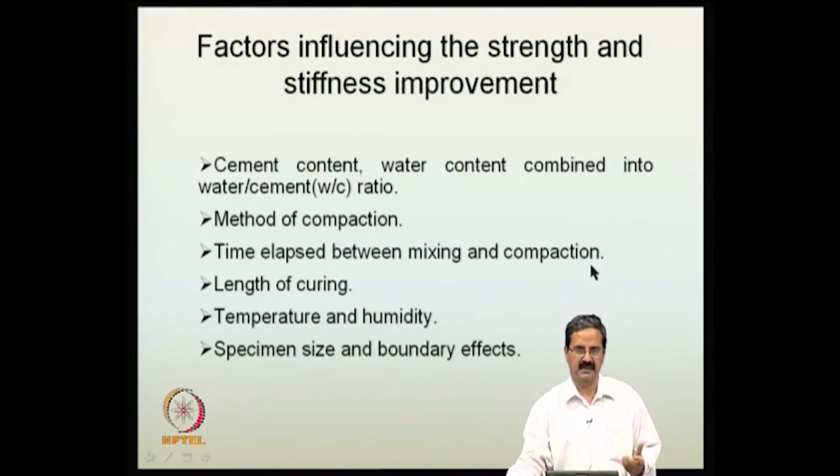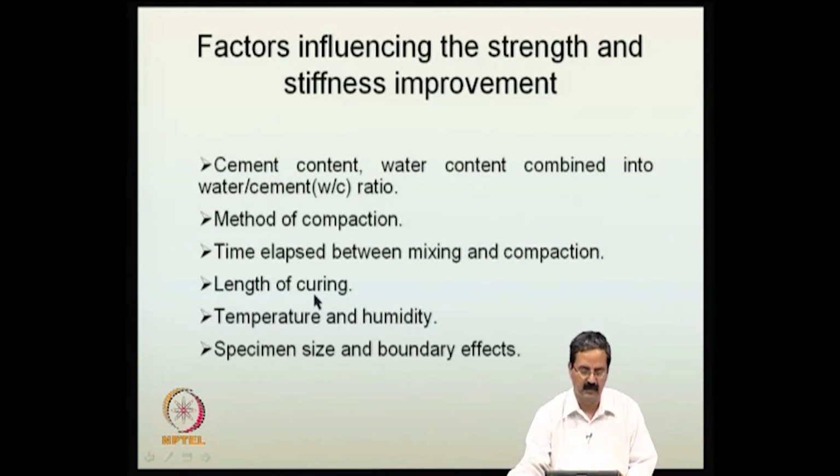If you mix cement plus soil and then take it later for compaction, that difference also matters, because the heat of hydration is an important variable. Then the length of curing; we are all familiar with cement concrete, and curing is very important because availability of water is important for the hydration to take place. Temperature and humidity are some more important parameters that are quite significant in attainment of the strength and stiffness required.